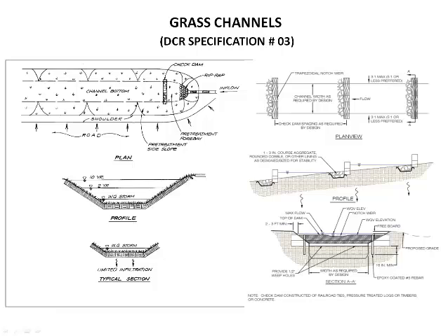Grass channels are a preferable alternative to both curb and gutter and storm drains, as a stormwater conveyance system, where development density, topography and soils permit. They can also be used to treat runoff from the managed turf areas of turf-intensive land uses, such as sports fields and golf courses, and drainage areas with combined impervious and turf cover, like roads and yards.